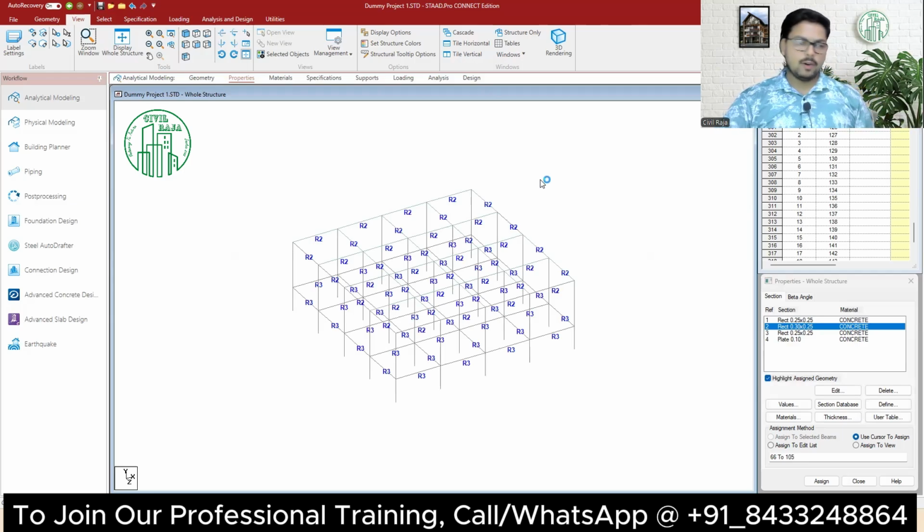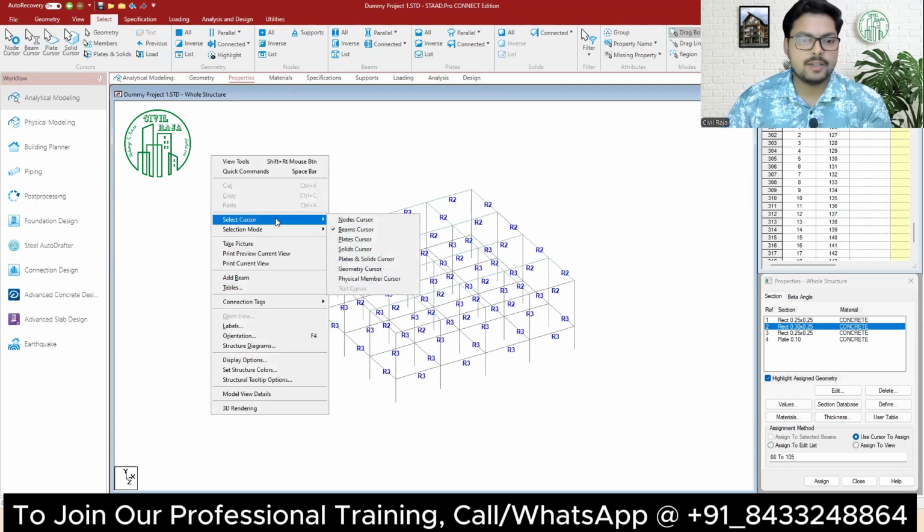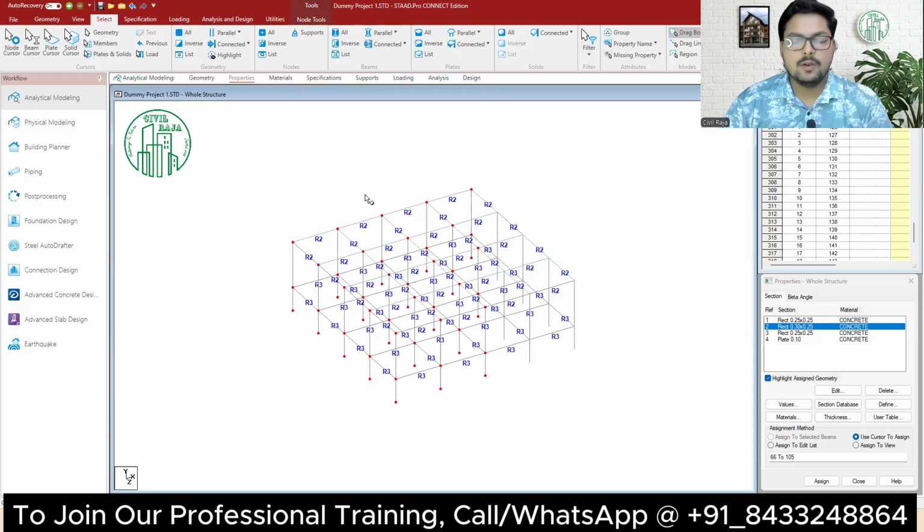Then comes the selection of the vertical members. In software we call them beams. However, the vertical members are columns in practical life, but the software calls them beams. So that's why I'm calling it beam over here, but it is basically the column. Now, for the selection, if you want to switch the cursor, you can right click and come to the select cursor, and then choose cursors from here, or you can come to the select over here. Like a node cursor I have selected, and you can see whatever is there in the nodes is getting selected.